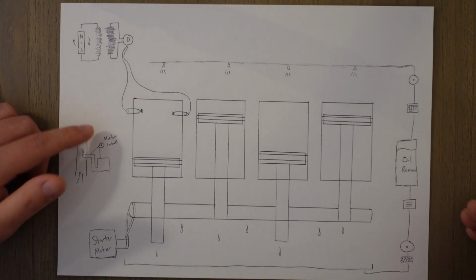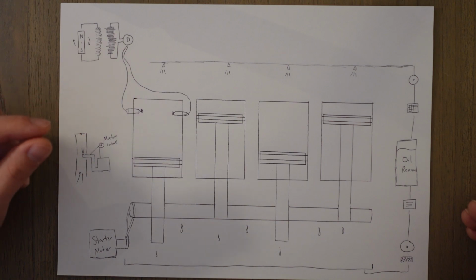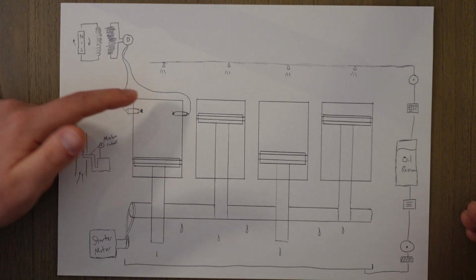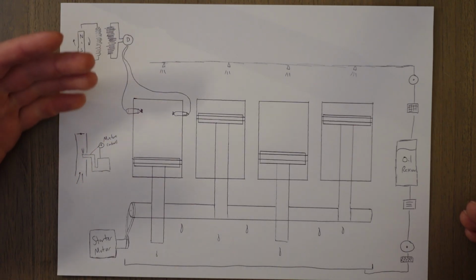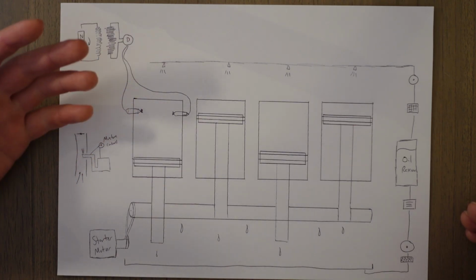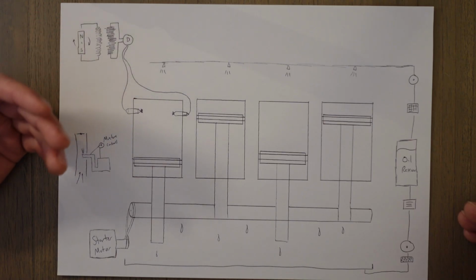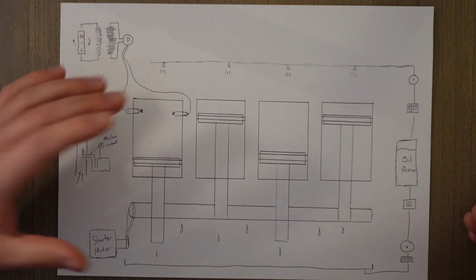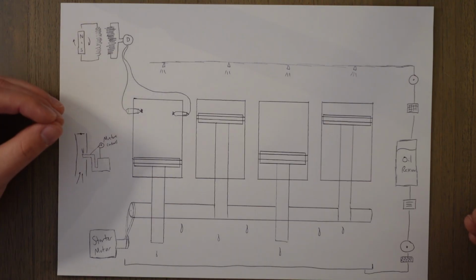Another way of delivering fuel is doing it via clever fuel injection systems, which are basically electrically controlled nozzles which will spray just the correct amount of fuel into the engine cylinders or into the air intake before the fuel-air mixture reaches the cylinders, and it's usually computer controlled and very clever bits of kit, quite common in normal modern aircraft. Another thing you can do with this air and fuel mixture is you can compress it.